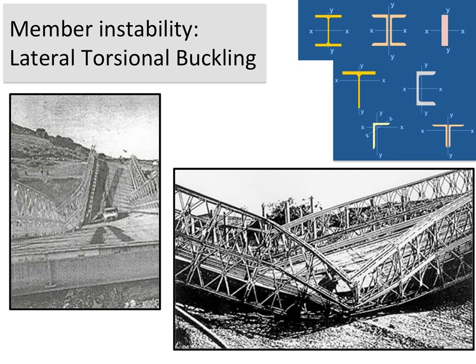Now, lateral torsional buckling doesn't just need to occur in wide flange shapes. I found this picture on the web, and here's one of those temporary bridges that every once in a while we have to drive over, and it appears that it wasn't a good day for this one. You can see that the bridge is basically set up so that the two sides here are the beams, and the top chord of this beam on the left side, say, is all, of course, in compression, and we've got some lateral torsional buckling in this extended long beam.